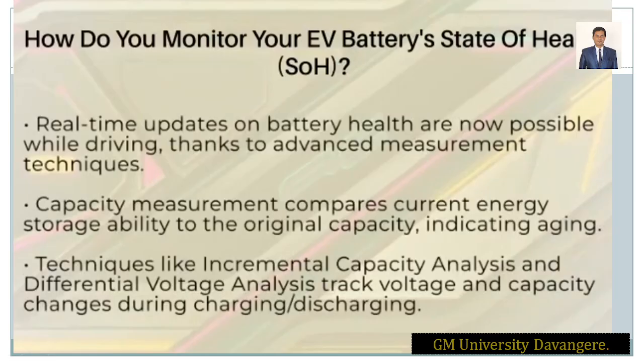And in capacity measurement, you should go for the SOH techniques, that is, measure using the SOH formula. You can identify the SOH in the BMS. Take the example of any EV company: the battery is around 30.2 kWh. When you bought the new car, after 3 years, if the BMS measures 25.7 kWh, then the SOH comes to around 85%. It means that aging is happening. That is how you measure the capacity.